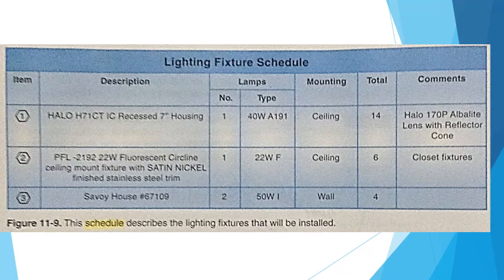Lighting and fixture schedule. This type of schedule lists the lighting fixtures used in the project. Each row in the schedule lists basic information for a single type of fixture. The information typically includes the number of fixtures required, the manufacturer, model number, and number and type of lamps. Each type of lighting fixture also has a unique mark, normally identified as a letter. The marks, which are included on the lighting plan, identify the location of the fixtures.